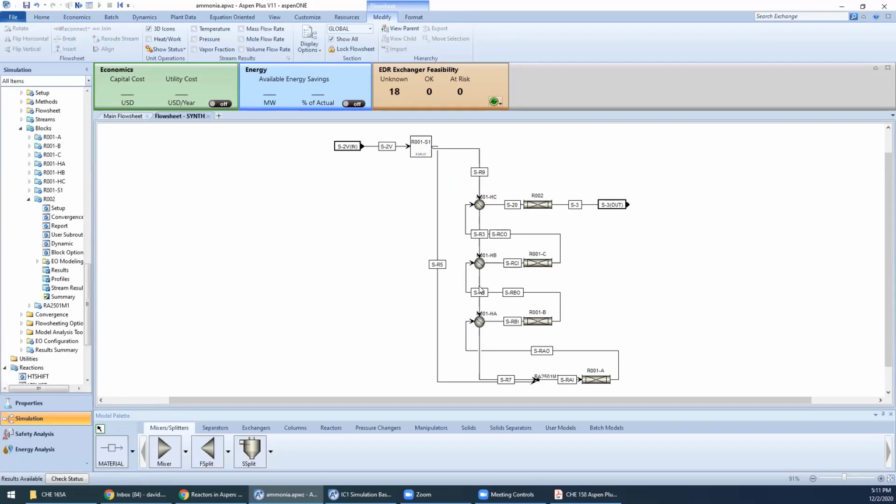And what this does is, this is a heat management technique called cold shots. Because the exit of these four plug flow reactors is a little too, I think, warm. And what these heat exchangers do is it cools it down to manage the exothermic nature of the reaction, so then it can keep everything in check and you don't get runaway reactions.